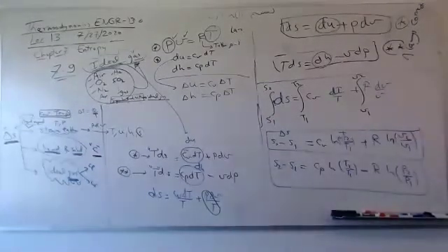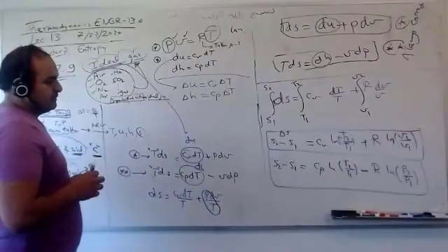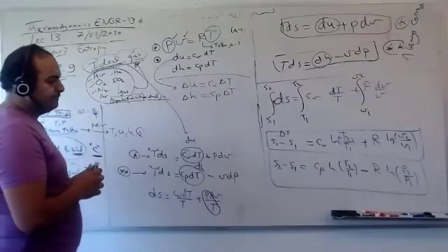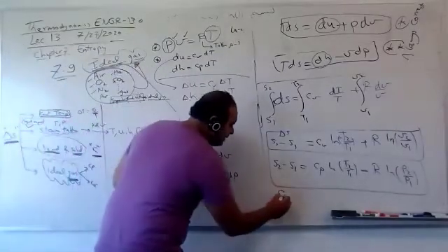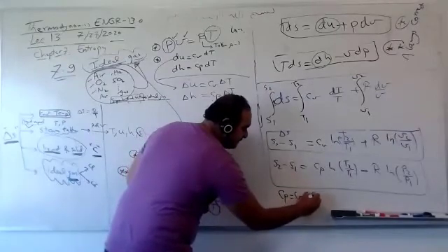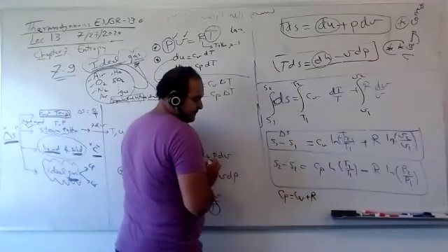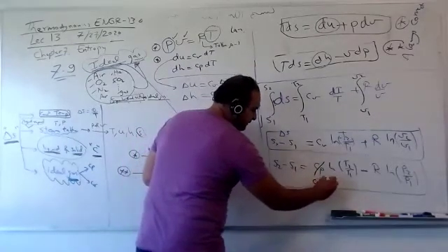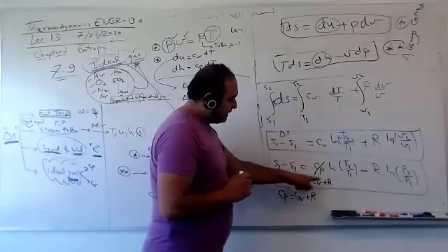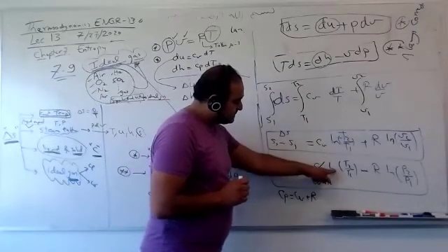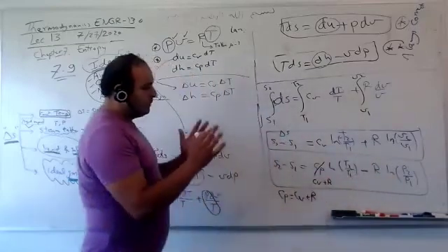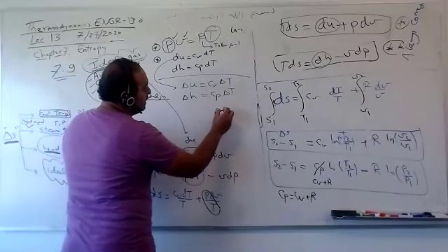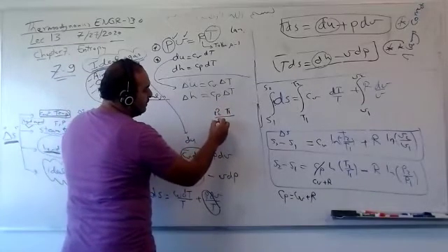Both are correct. Look at this. The first equation is exactly the second equation. You know how? Do you remember when I said Cp equals Cv plus R? Do you remember this, guys? If you replace here Cv plus R, Cv times this gives this. R times this minus R times this. If you take R as a common factor, you will obtain P2 T1 over P1 T2.